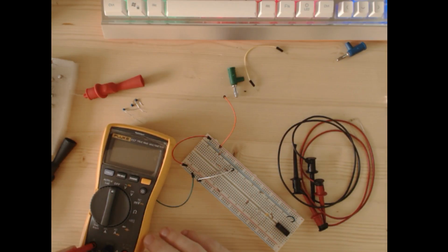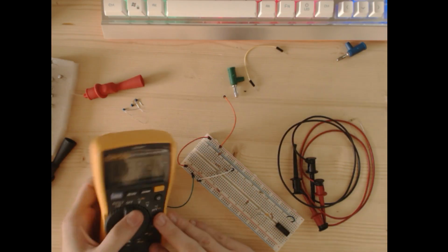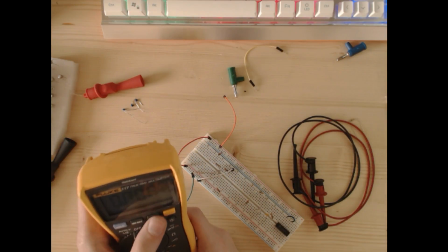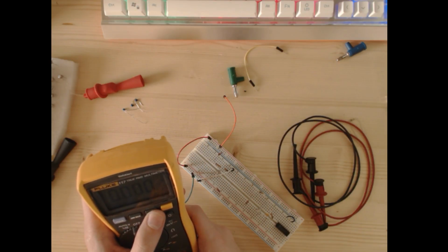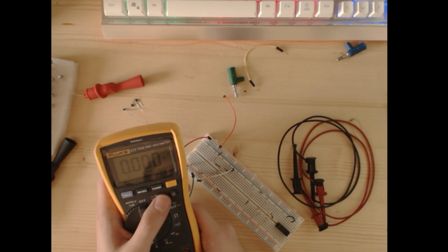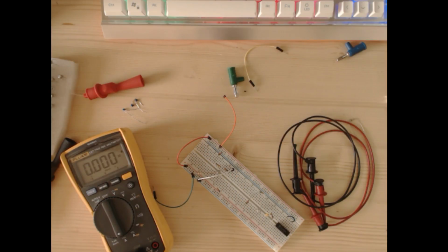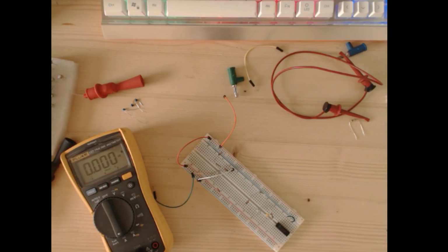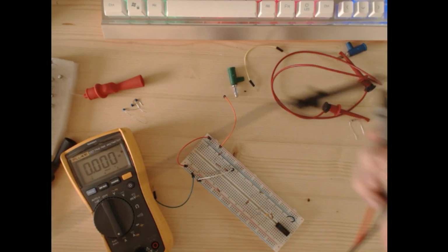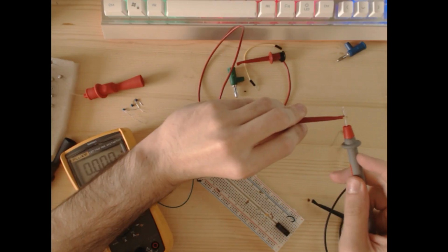So this can measure in amps, and I don't know if the range is 10 amps, 6 amps, 6 or 10 amps. Probably I'll be able to see it. So we want to measure first the current going into the base. I'll put this on my black lead like that, and this on my red lead.